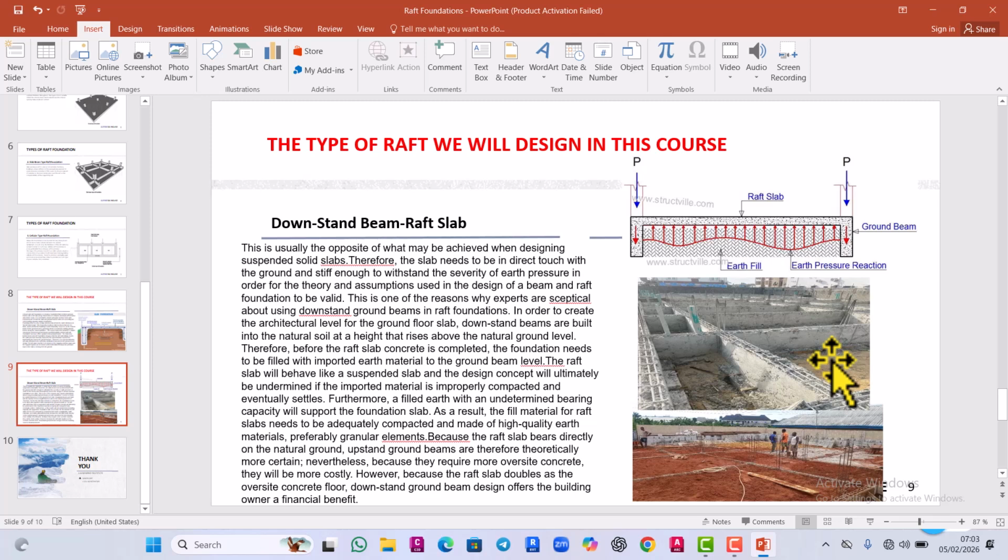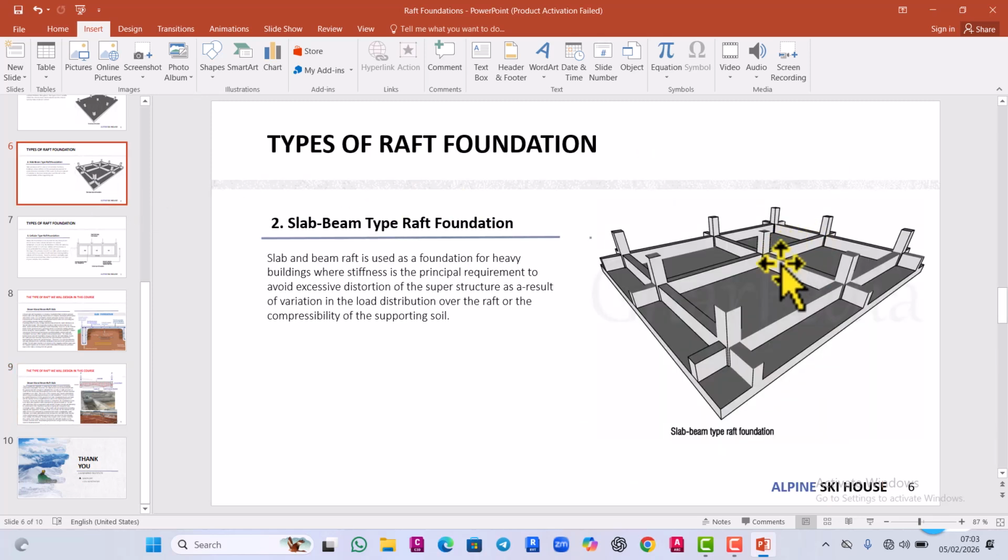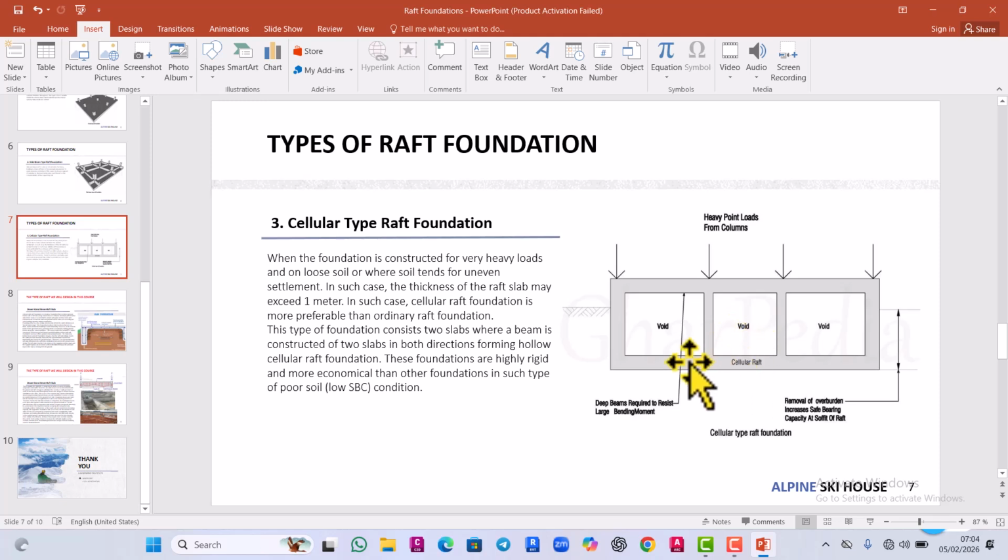Because once we go like this, when we come to the ground floor, we still need to do what we call the oversight concrete again, which is now you do the slab first, come again, oversight concrete again, like this now. So you do the raft slab, oversight concrete. Then here you backfill it. Once you backfill, you now do your oversight concrete. So people say, okay, it's what?